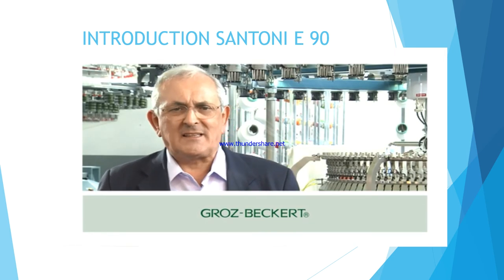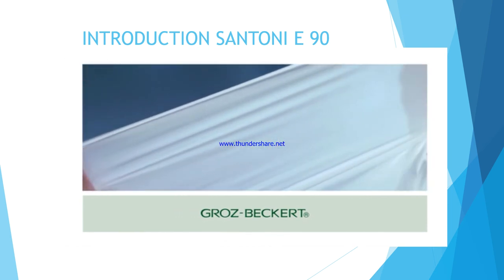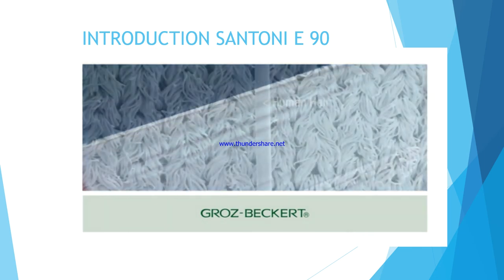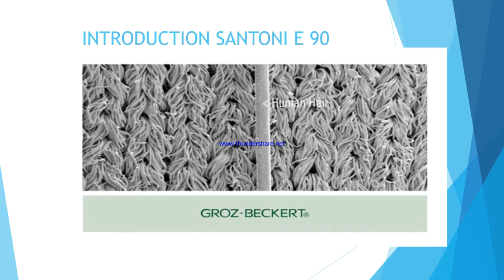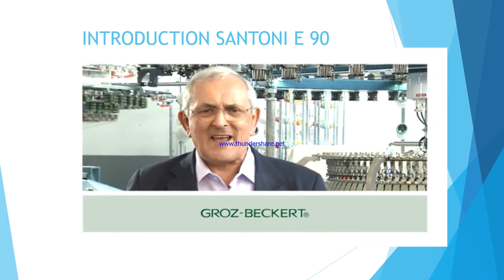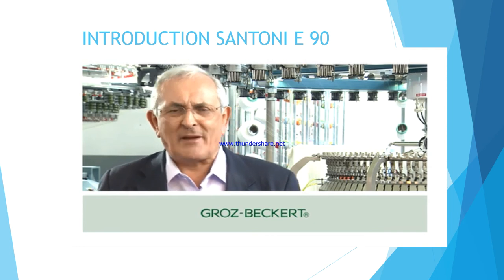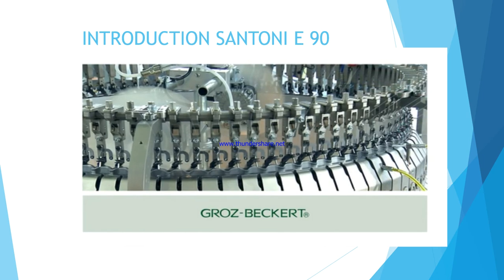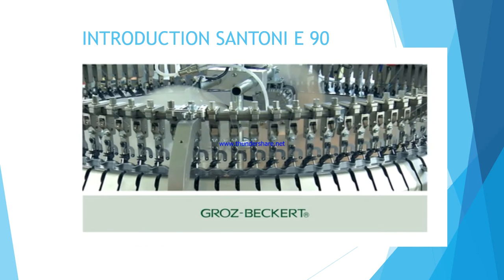The Atlas system prevents the fabric defects often caused by the sinker, vertical lines, irregular stitches, etc. A very clear problem with extreme gauges. In the traditional jersey stitch, the sinker movement, which is needed to facilitate the stitch production, exerts considerable stress on the stitch, with an ensuing oversizing of the loops. In contrast, the stitch made with the Atlas system is narrower and more compact, just because of the absence of such an obstacle.